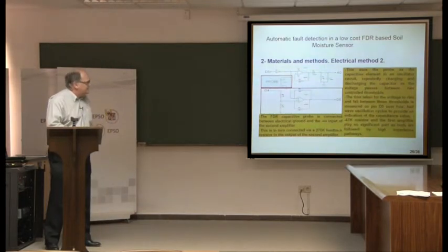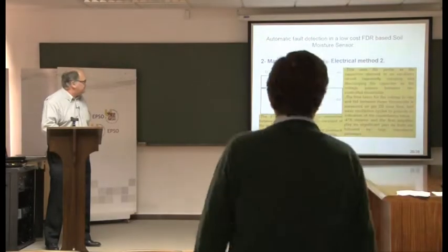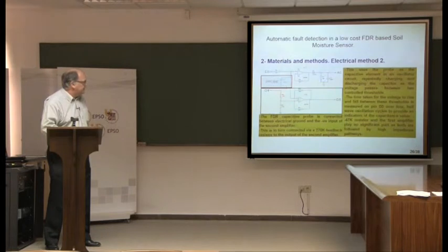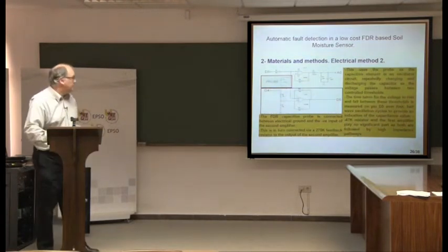Microseconds after doing that result, basically we now use the probe in a different way. This capacitor is now the controlling element of this oscillator. Basically this capacitor is charged, which changes the threshold level of this detector, which then switches it into discharge mode, etc., and the cycle just repeats so that this circuit now oscillates. The time it takes that capacitor to charge is measured, both the charge and the discharge time, on this pin of the microcontroller.